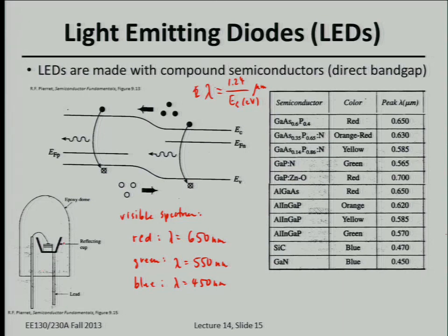And here's a little picture of an LED. You have light coming out actually in all directions, and this is a reflecting holder that's also potentially used to bias one side of the PN junction. Light comes out and is reflected, and this package is shaped to help aim the light out at the viewer.